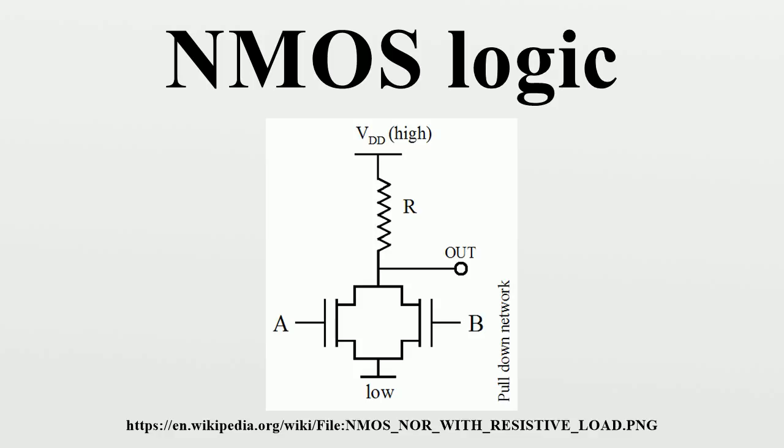The MOSFETs are N-type enhancement mode transistors, arranged in a so-called pull-down network between the logic gate output and negative supply voltage. A pull-up is placed between the positive supply voltage and each logic gate output. Any logic gate, including the logical inverter, can then be implemented by designing a network of parallel and/or series circuits,